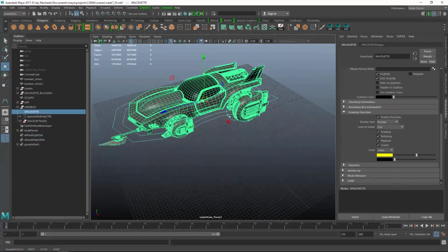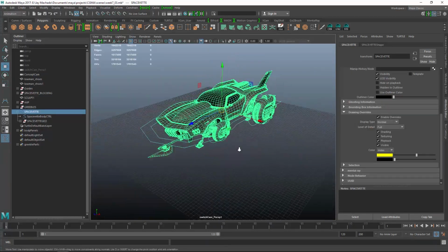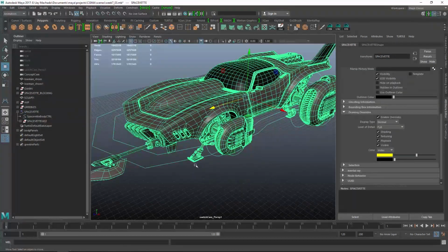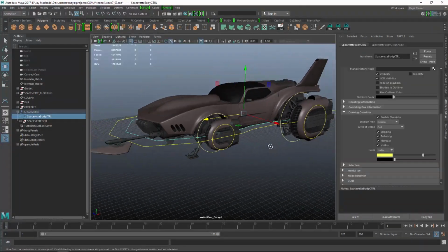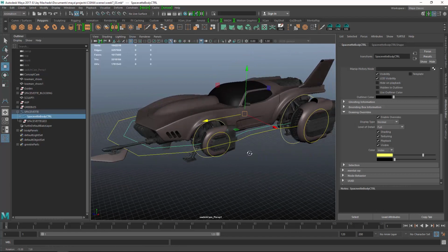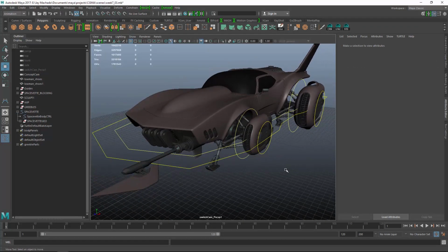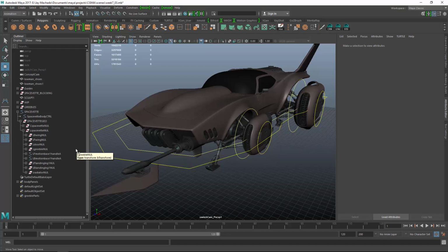And now you can see if I grab my main null, I can move it around. And this one, though, is going to just control the body, so we can actually control the body kind of independently of the landing gear feet, and that'll give us a little bit of bounce and compression when we do animate a landing sequence or something.